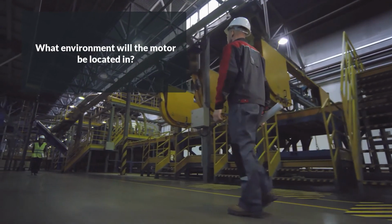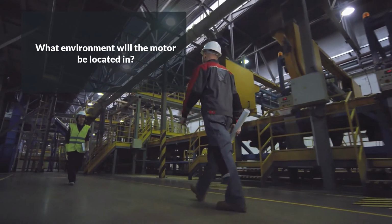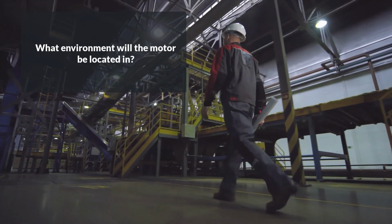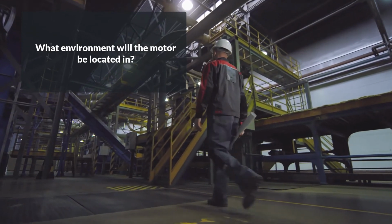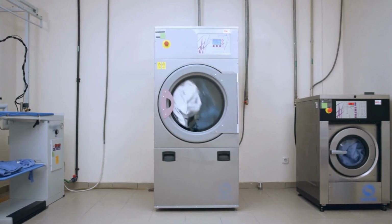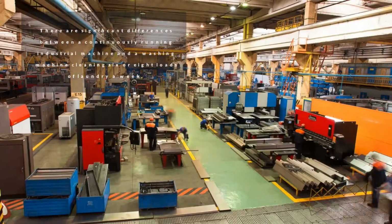Finally, in what environment will the motor be installed? The motor selected for industrial applications must be robust and capable of handling the environmental conditions. Don't make the mistake of specifying a single-phase AC induction motor, often used on a small appliance such as a washer or dryer, to control small loads on a machine.